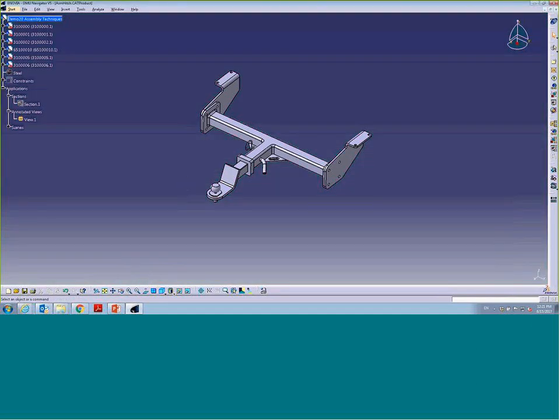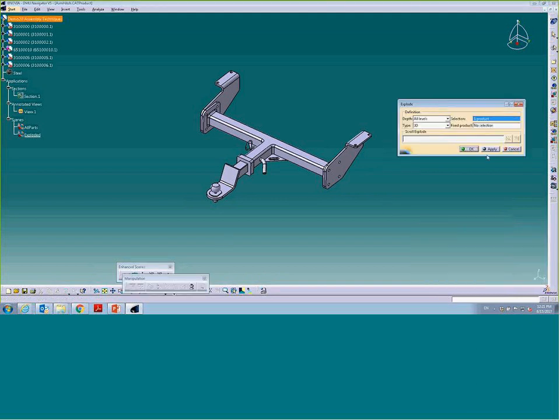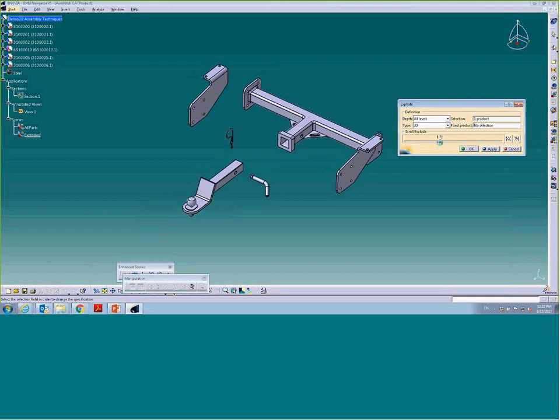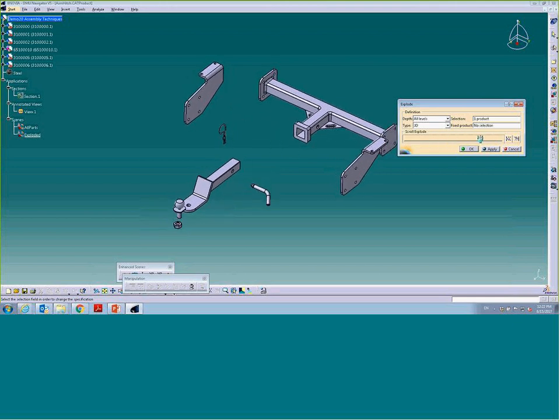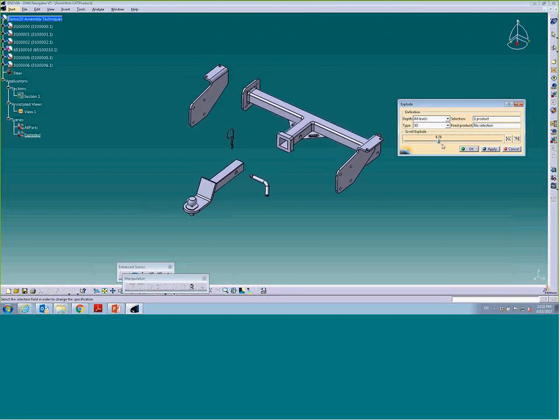So basically, this all parts scene is needed for me to be able to bring them back together. Now I'm creating an exploded view. I'm going to create another scene, called explode. Okay, hit OK, and reload tool. So explode. If I apply, they all go apart. If I move the slider, they kind of explode. There was a sub-assembly and a main assembly, so it unexploded the main assembly first and then the other parts.